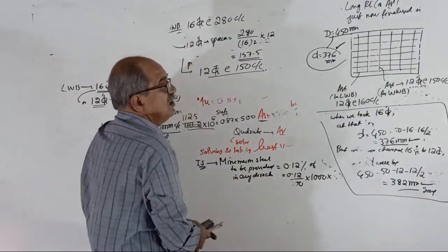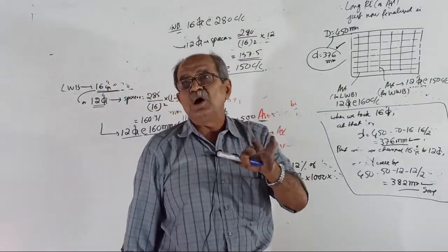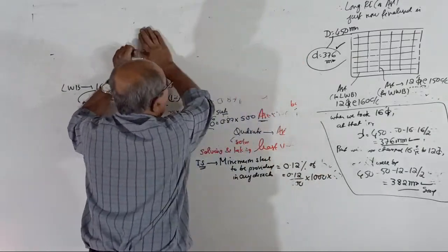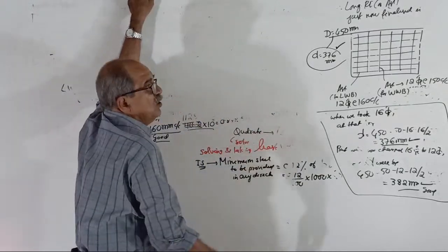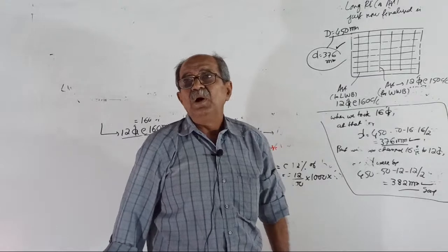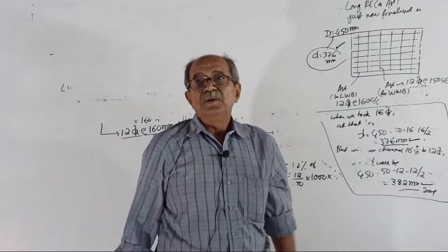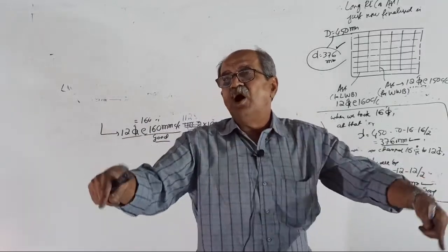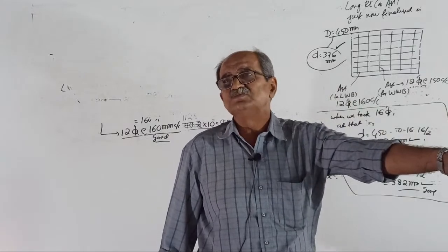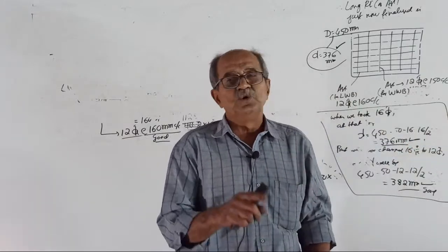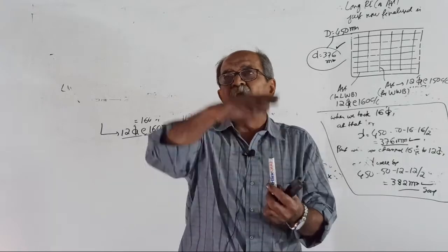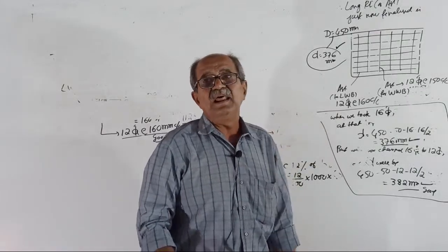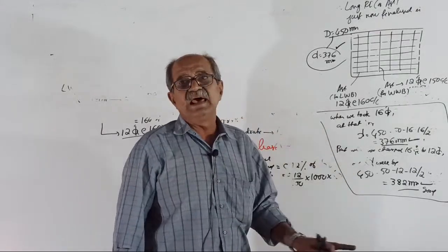Start. Now, the most critical part of the slab. One more thing is there now. As soon as this example is over, I will tell you, when you design the slab by ETABS and SAFE, you need not do the pressure check. Footing size you have to fix. For that, I will give you an Excel sheet. You should decide the footing size not based only on P, but with P, M1, M2, as their pressure change is there. I will explain to you. Don't worry, I will prepare that Excel in the class.